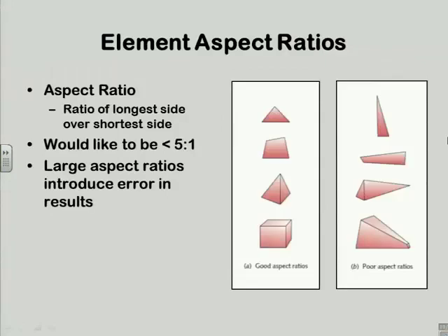Yes, go ahead. Also, when you're creating the mesh, you can have a good aspect ratio, but you also have to make sure that sometimes for long, straight elements, you have more than one level of elements. Most FEA programs will throw an error if you have a long beam that is only made up of single elements along the length.